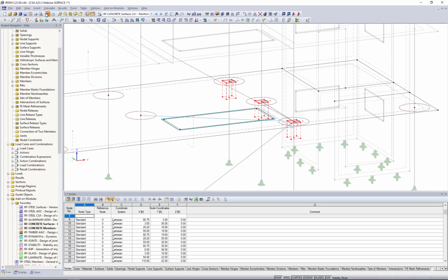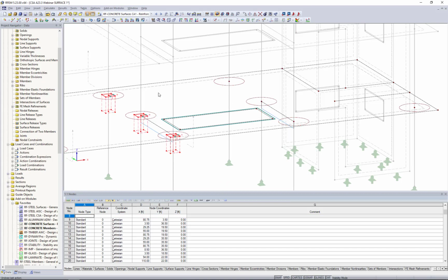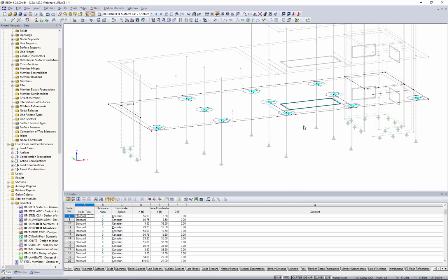You can see I accidentally dragged something. Let's undo that. Let's try this again. We'll just do each one individually, no problem. Using this drag and drop feature, making a quick copy of the second column line, and finally we have our last one here. We can delete this unneeded one up at the top. Okay, so that's how we can make quick copies of those average regions. You can even select this entire floor and copy it up to the second floor as well.